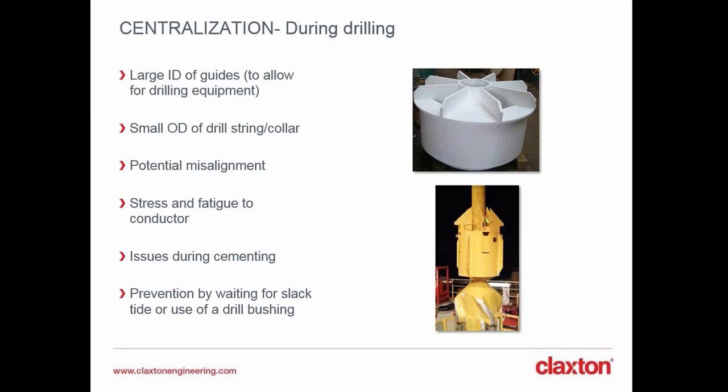And a way to do so is waiting for slack tide, and just making sure that your drill string is central within the lower guide before you actually start spotting. But another way of doing this as well is by making use of a centralizer or drill bushing. The purpose of this item is to centralize your string within the lower guide of your offshore platform or drilling template, if there's one. The alternative to this would be, as I said, to wait for slack tide, and then you'll have to lower quite carefully to the seabed, and the ROV should monitor the operation as well, just to make sure that the relative position of the drill string within the lowest guide before spotting is central.